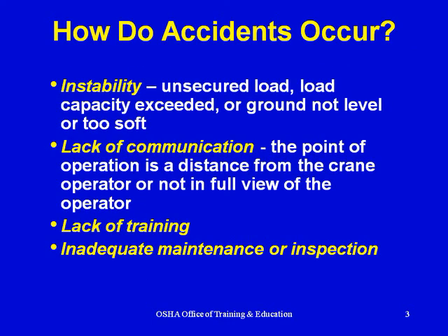How do accidents occur? Instability, unsecured load, load capacity exceeded, or ground not level or too soft. Lack of communication. The point of operation is a distance from the crane operator or not in full view of the operator. Lack of training. Inadequate maintenance or inspection.